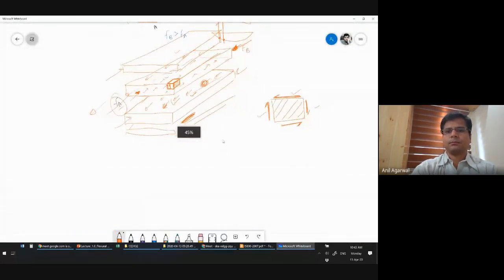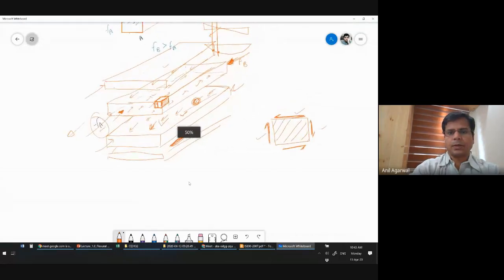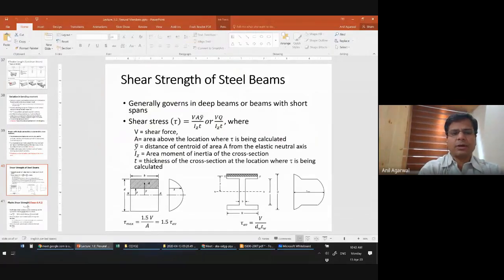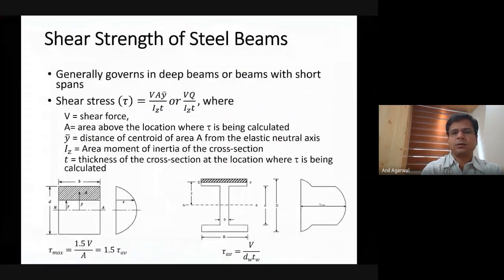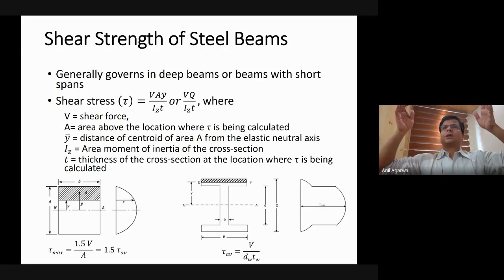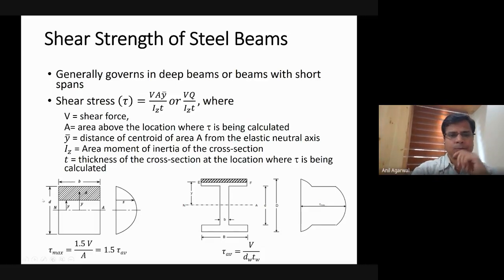Fine. So from there we can understand why the shear stress at a level is proportional to A y bar, which is saying the more area you have above it, the larger the axial force difference in that area will be. That multiplied by that distance will give you the value proportional to the shear stress here, and that's how you get this parabolic profile.